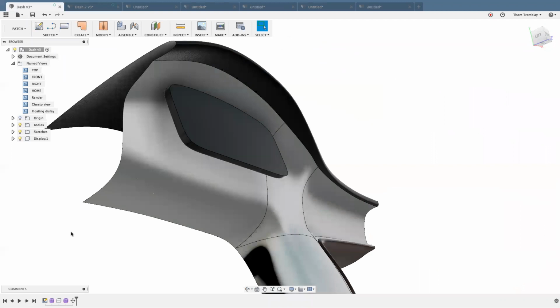What you can do with that then is take the mesh that's defined, bring it back and create it as a T-spline body. And what you might find is a little bit of inspiration to help you come up with a really unique looking shape that, based on the engineering requirements, will still work. But it's not just a vanilla triangular bracket or a simple rectangle. Suddenly it's got a very functional form as well. That might be a place where simulation could help.